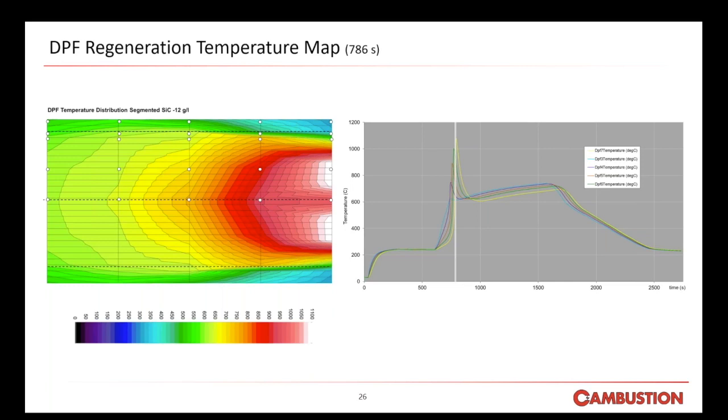The leading cause of failure within a DPF is either an axial or ring-off crack. The reason for plotting the axial and radial thermal gradients, which we'll see later on, is to try and relate these to failures we see from real-life exotherm tests.